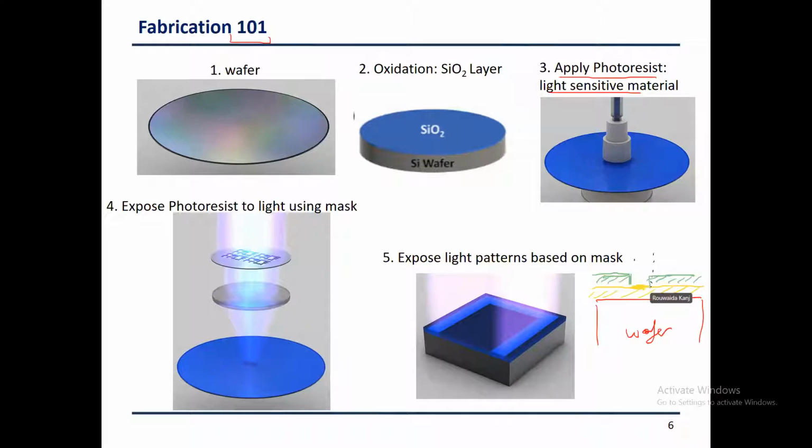And now if we put another chemical that will spill or flow on the wafer, the places where we have the photoresist will be protected. Okay, so this will be protected and this will be protected, and this portion will be exposed and it will erode, it will be erased. So we will remove it. There might be some erosion at the peripherals, okay, but we will end up with mainly this portion of the oxide remaining that was covered by the photoresist.